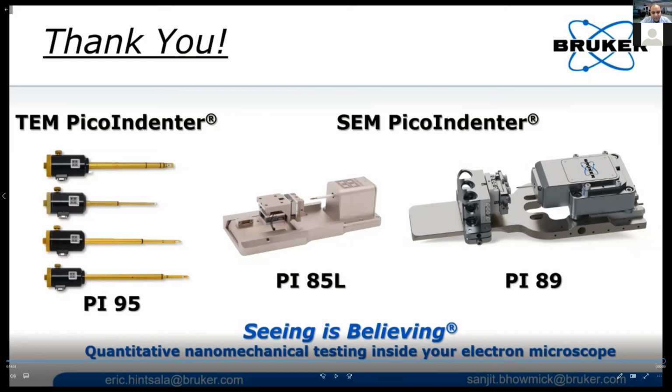There's another follow-up question from Dr. Sampath Kumar, that the tribological studies that you mentioned were done under dry conditions. Can it also provide friction data? It can give friction data because we have both a lateral transducer as well as a normal transducer. We can measure the lateral force and normal force, so we can get the friction data. When we did that, it was at much higher loads. You can do it at lower loads, so it may be just a friction condition where you don't have much plastic deformation, and under that condition you can measure the friction as well.